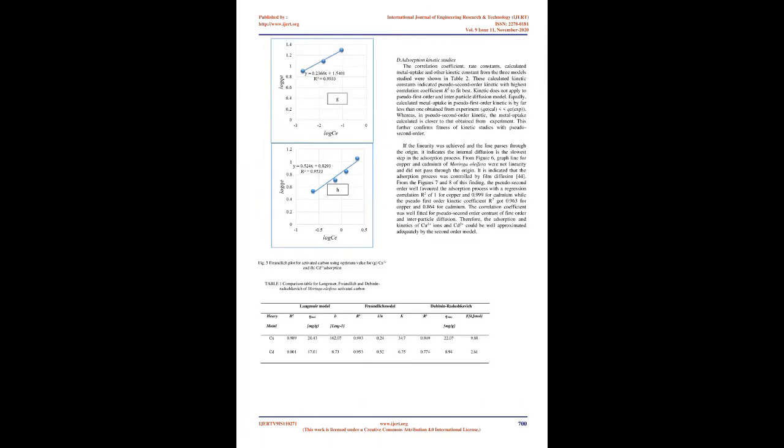Large and well-developed pores were obtained from the prepared activated carbon under optimum conditions, at 700 degrees Celsius temperature, activation time 60 minutes, as well as char, ZnCl2 and H2SO4 impregnation ratio 1:5. It might have occurred due to the use of a chemical activating agent. The adsorbed metal molecules got to fill the pores from the adsorbent surface to the inner pore, and at last they bind at the available sites on their surface. Surface area and pore volume development could also happen during the pyrolysis process. These well-developed pores were an important factor in adsorbing the maximum heavy metal from wastewater.